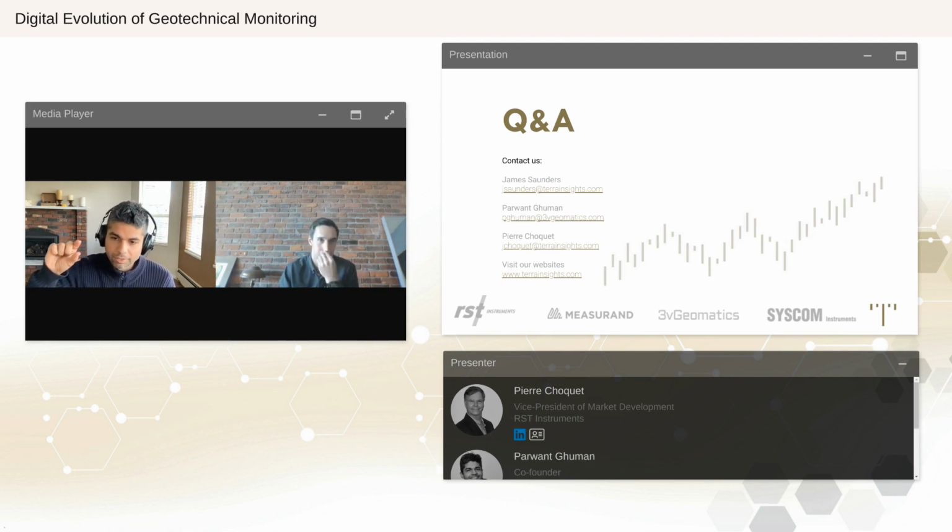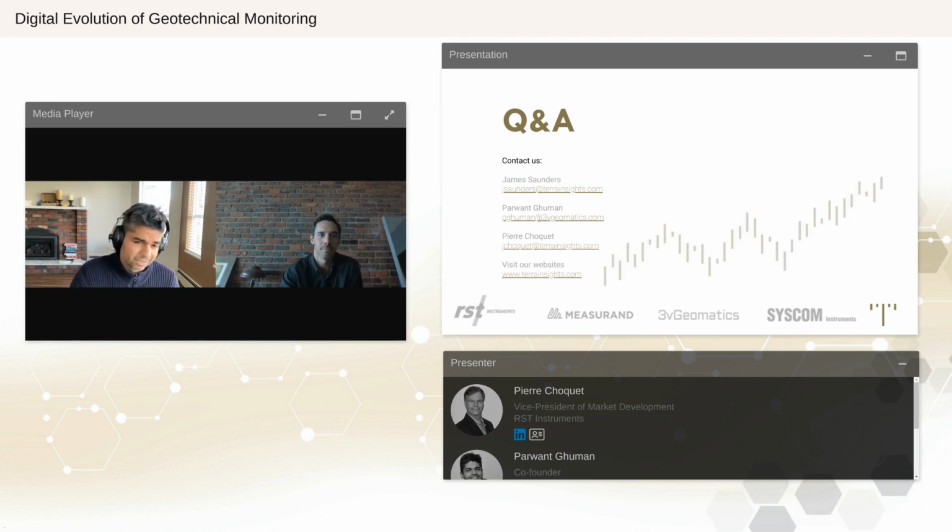If you're using a short wavelength, so 15 millimeter wavelength or 30 millimeter wavelength, then you're going to get down to your millimeter precision or 5 millimeter precision. But if you're monitoring densely vegetated areas, you can't use these short wavelengths. You have to use the long wavelengths to penetrate the vegetation and make measurements from the ground. So now you're using a much longer wavelength, like 24 centimeters, and you're measuring fractions of that.